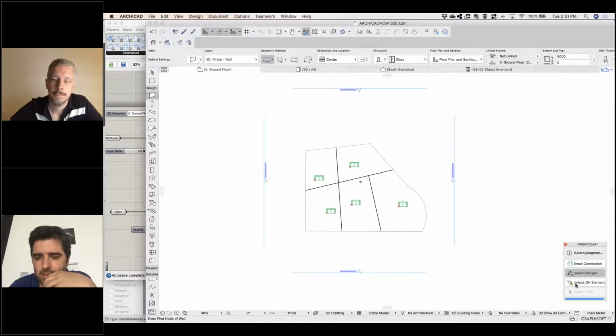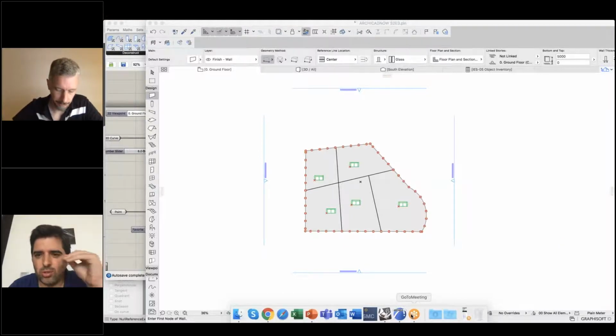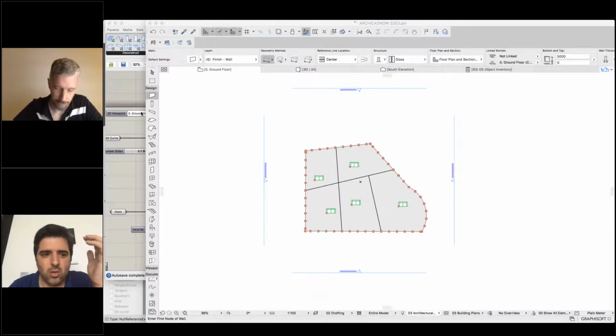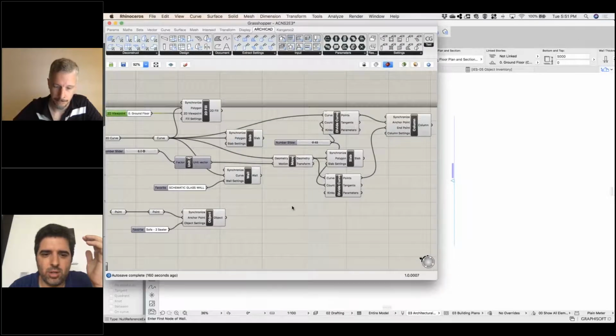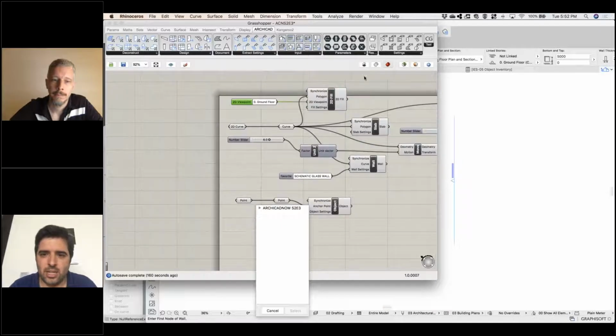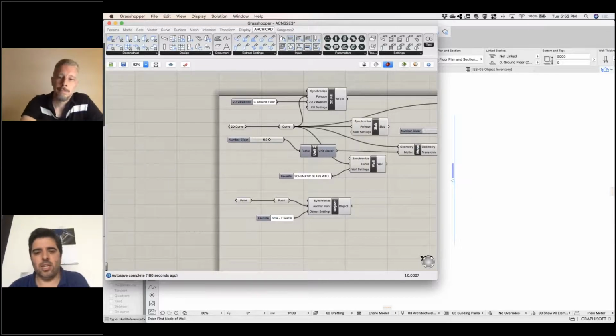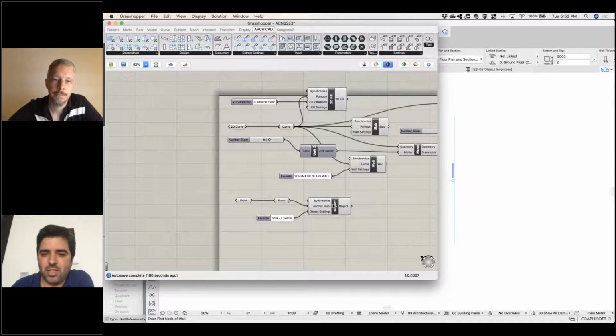Marcelo? We can, yes. Chidam here. Yeah, there's a question from Ian and Catherine. What is the home story of all the elements? Okay, by default, the elements will go to the home story where they are placed. One of the settings that we can put on the elements is exactly that. So when you get the settings, it's saying that they will belong to a certain home story. So that's why I like to use the favorite, because the favorite can contain that data immediately.